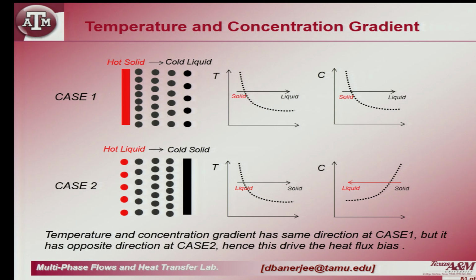Okay. Now, how many of you have heard about this term called Dufour effect? Any of you heard this term called Dufour effect? How about Soret effect, S-O-R-E-T? Any of you heard Soret effect? Come again? Thermal diffusion. Because there is a temperature gradient, it causes a mass of material to move from hot to cold, because there is a convection that has been set up.